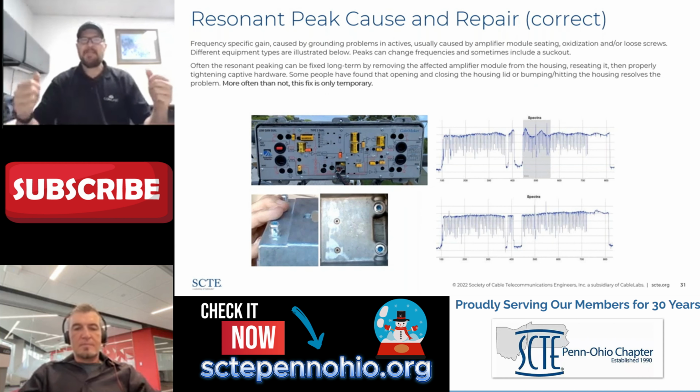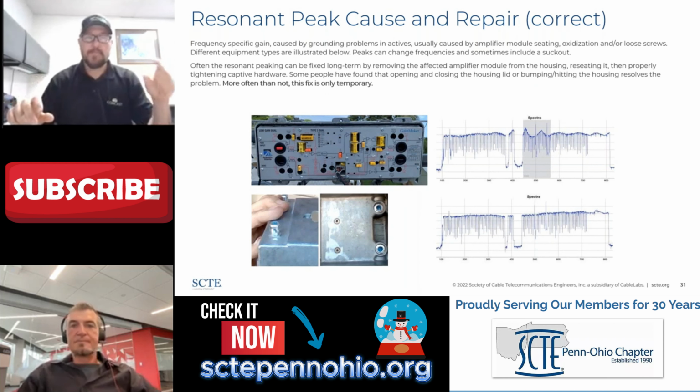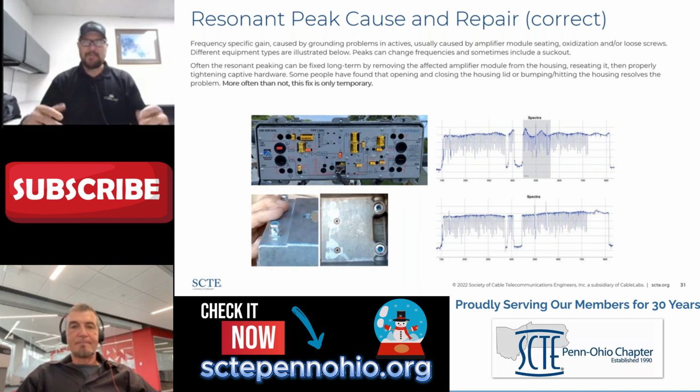So in this case, taking the module out, checking for corrosion, ensuring that the seizure lugs in the housing are tight, making sure that there's no corrosion on the connectors on the back of the module, and then properly tightening the module retainer screws into the housing and properly closing the housing will result in the response that you see on the bottom, which is everything's nice and flat.